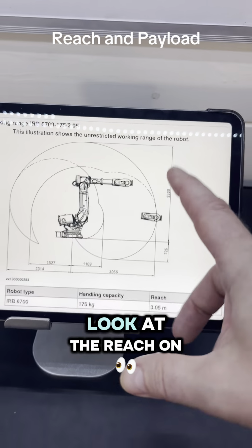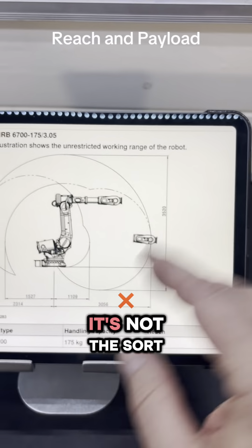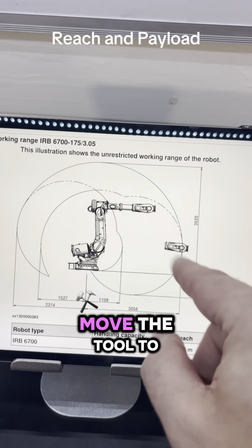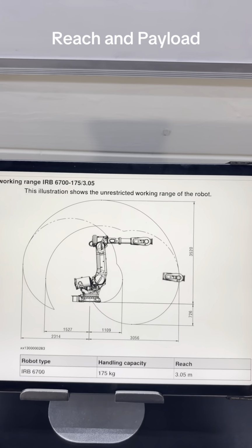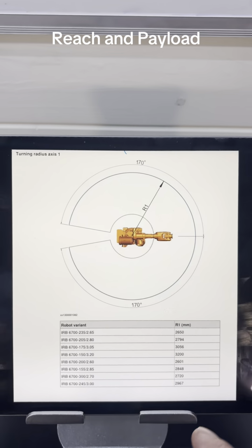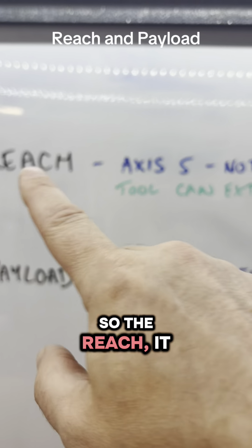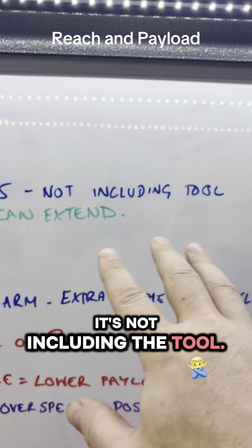So the longer the reach, the lower the payload. And so when you look at the reach on an ABB, it's to the middle of the wrist. It's not the final end point of the robot. It's the point at which the robot can move the tool to anywhere in that space effectively. And the tool can extend that. And as I say, it's kind of a donut round the robot. So the reach goes to axis 5. It's not including the tool.